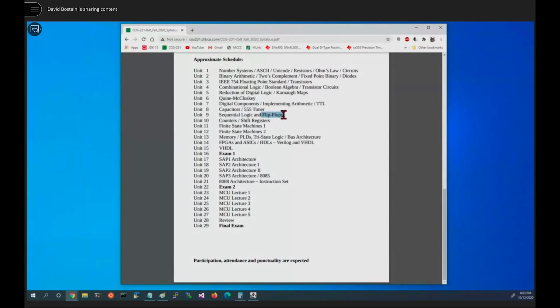I know I left you with a kind of floating assignment about a flip-flop and some analysis on it where we were not using a capacitor, but nevertheless we were going to get an edge, so we could consider that flip-flop to be an edge-triggered device and actually call it a flip-flop and not a latch. Remember that. If I call it a latch, unless I happen to be being goofy at the moment, I mean level clocked. If I call it a flip-flop, I mean it's edge-triggered.